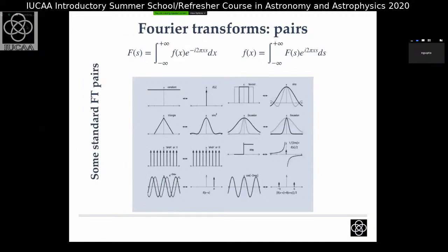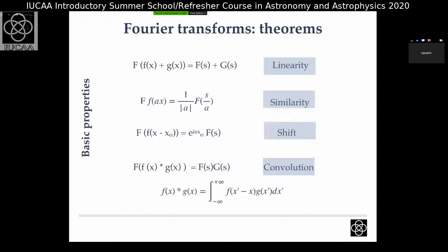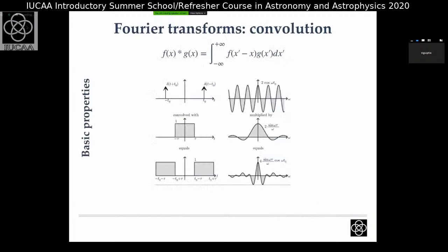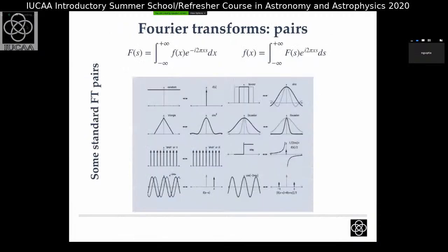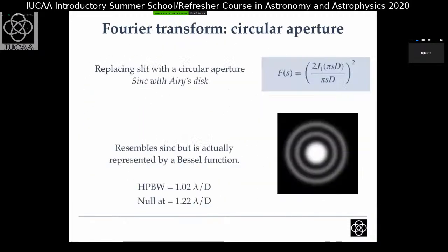So, starting simply, I have a box function to represent my aperture. And then I have another box function which represents my feed, and it is a much smaller one because, let's say, my feed is much smaller. Of course, that is practically true also. So what I'm doing through aperture blockage is subtracting these two functions, right? I can use the linearity of the Fourier transform property, take the Fourier transform of these two functions, subtract them and square them. Then I would get an obscured Airy pattern, right?